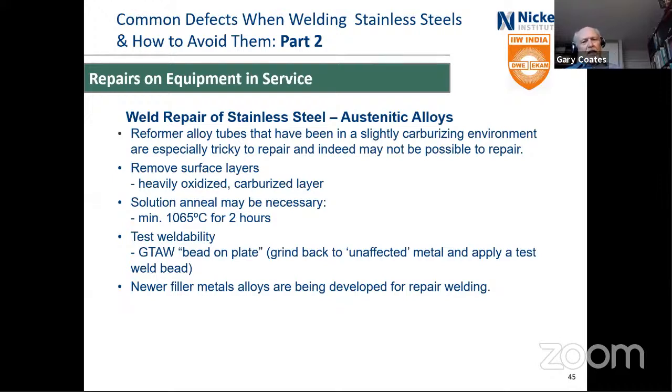And typically we do a test of weldability, a TIG bead on plate weld. If you do get cracking, you grind back a bit more, do it again until you get one that doesn't crack. And with reformer tube alloys, there are new filler metals being developed for repair welding. A group that I belong to called MTI, Materials Technology Institute, has several programs on weld repairing of reformer alloys.